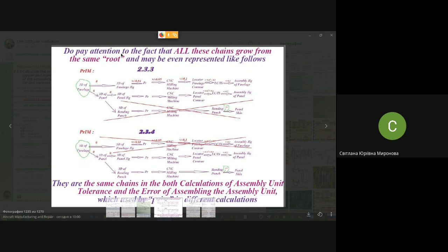Calculating the tolerance limits here: the designer hasn't given you limits for your unit. He, she, whatever. The designer gave limits only for the aggregate. You need to recalculate the aggregate limits to the most strict one for your own tolerance.